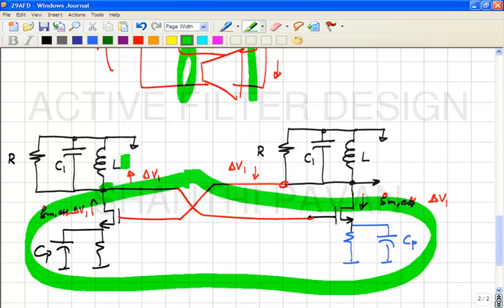So when I say you will see oscillations, you will see common mode oscillations, because even though a single transconductor is stable and nice because you've designed the phase margin, all very well, the moment you make two transconductors and put them as a gyrator, there is a common mode positive feedback loop formed because of the way the transconductors are connected.